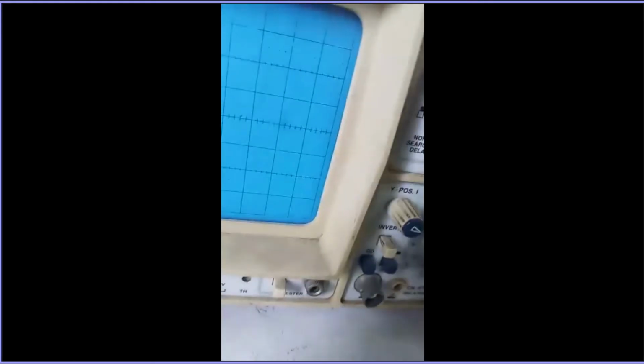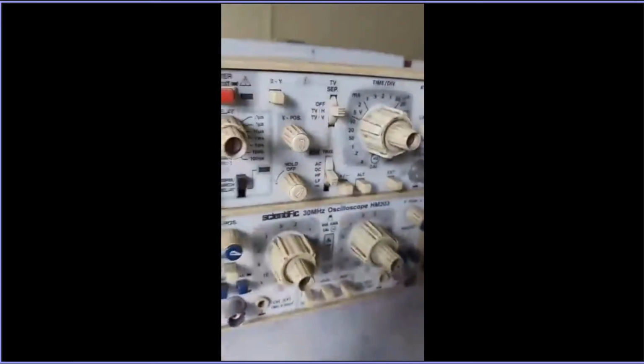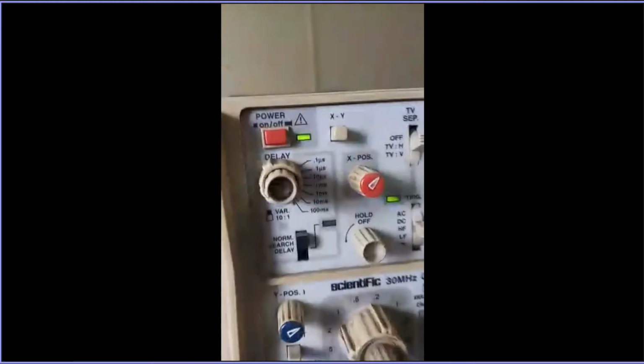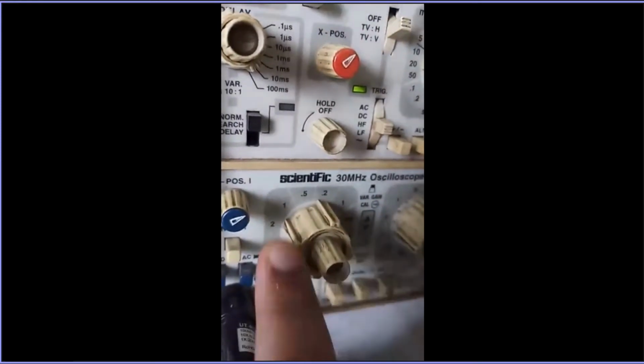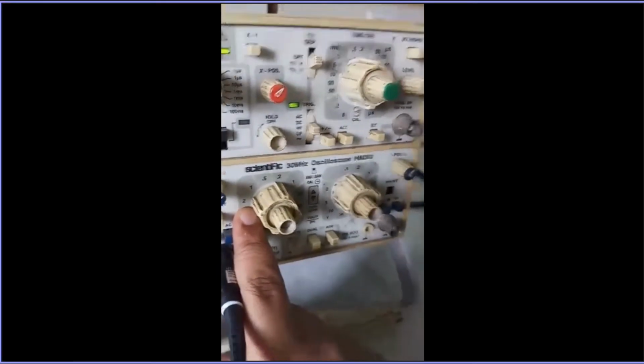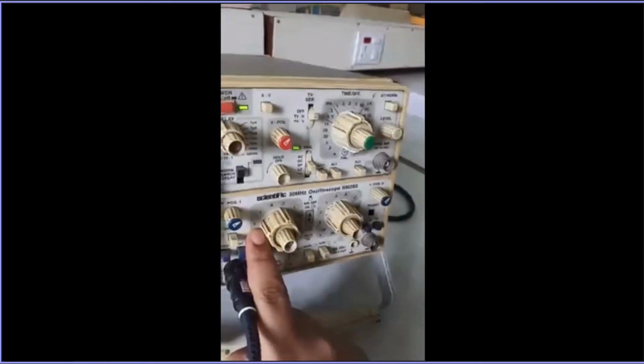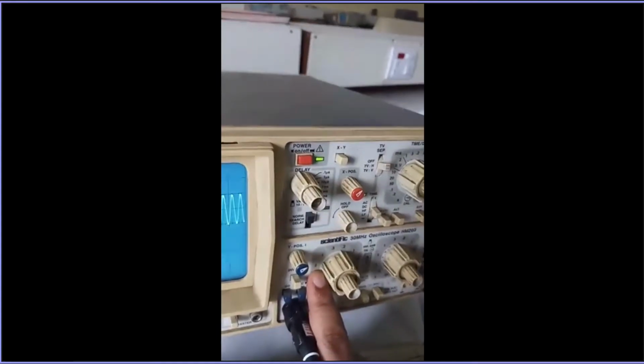Because we have changed the time per division, but we have not changed the voltage per division. It was 2 volt peak to peak that time also, and even now it is at 2 volt peak to peak, right? So don't worry, you keep it as 2 volt peak to peak. Here you can see still at 2 volt peak to peak. Here it is 2 volt peak to peak. So, 2 volt peak to peak, right? So you have the blocks, you have to multiply this by 2, so it will give you the voltage value.